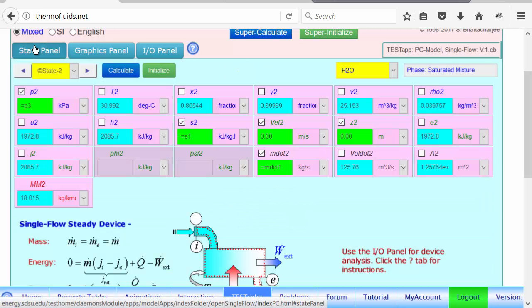Let's go one step beyond and see. So what is an isentropic efficiency? That means if everything is the same, and just friction was eliminated from the turbine, you're still delivering steam at the same pressure at the exit, but the temperature could be different.